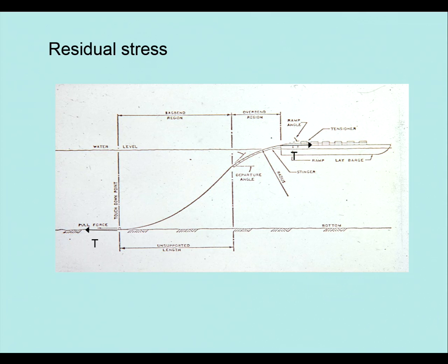And that's how we used to do a lot of analysis in the early days. But as the water depth got greater, we found that we were buckling pipe too often. So one thing we questioned is, was that tension actually the horizontal component of it? If I'm applying the tension up here, like a lay barge, then that is the horizontal tension.